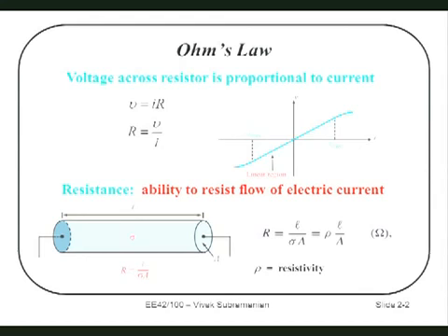Question? Does it matter where the connection points are? Because when the resistors are much wider than the wires, does it matter where? Yes. Good question. So the point is, let's say I just had a little point contact over here connecting to this really wide resistor. Does the position of the point contact matter? Absolutely. And that leads to something called contact resistance, which we are going to completely ignore in this class. Okay? But yes, it does matter, very much.